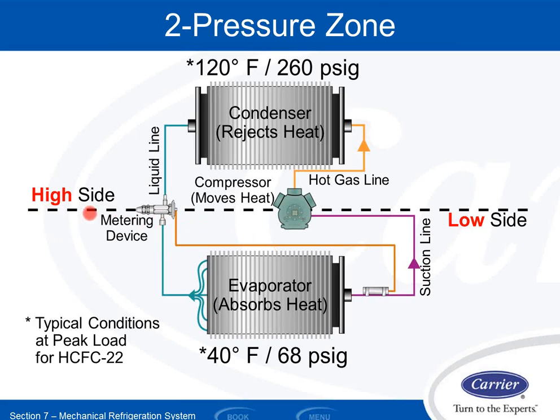So I could literally draw a line through the refrigeration cycle between the TXV and the compressor. And by the way, this is an old recip compressor, which is why it looks like a hideous, ugly beast there. But I draw a line between those two. Everything on the bottom of my drawing right now is my low side pressure. Everything on the top side is my high side pressure. The low side pressure is going to absorb heat, in this case out of my airstream, and I'm going to then pump that through the suction line, which is in purple over here.